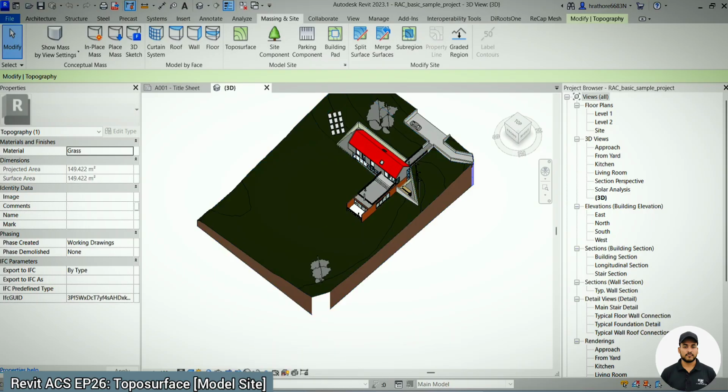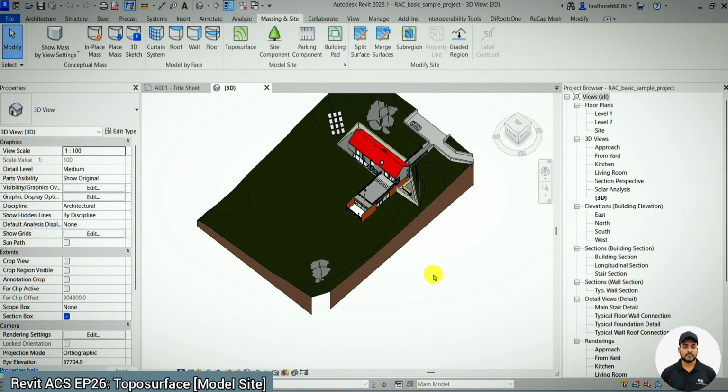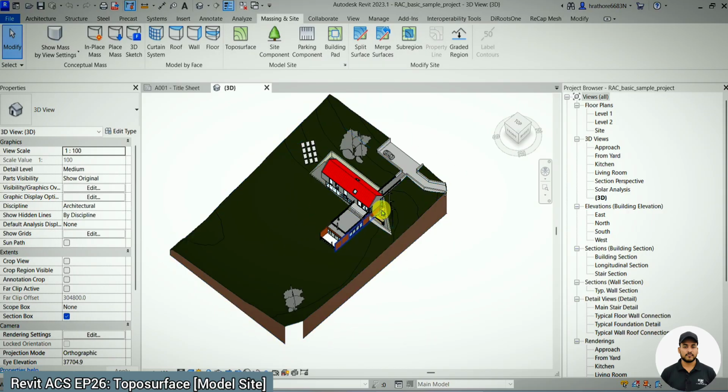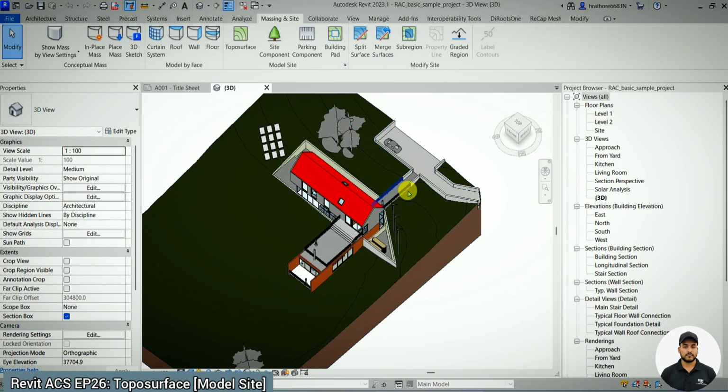It will help you in site planning, in checking the levels and slopes at different points, and in building placement, where you want to place your building. This terrain helps you decide that particular zone or location. It helps in the excavation part, how deep you want to excavate in a particular area. Further, on this terrain you can host roads, beds, and site components as per your requirement.